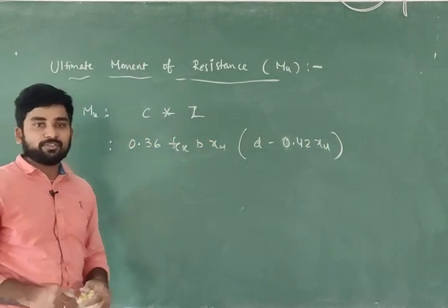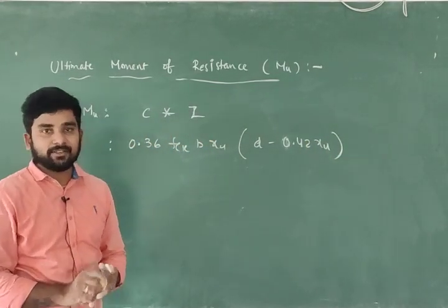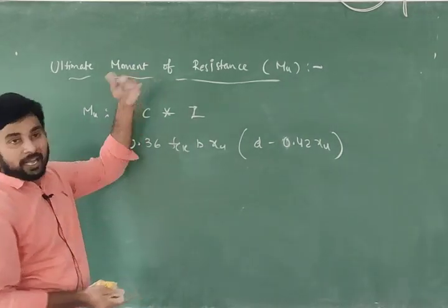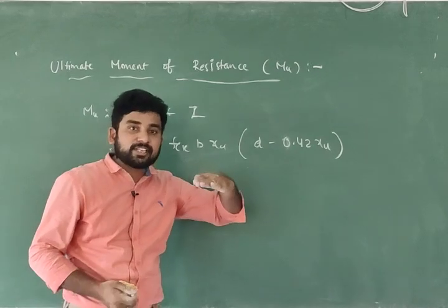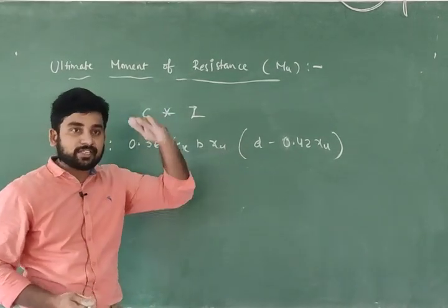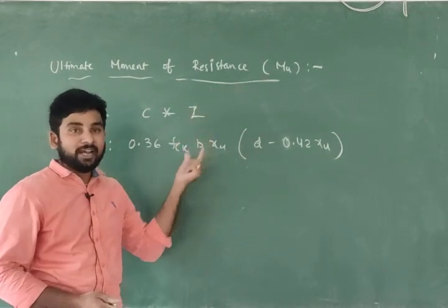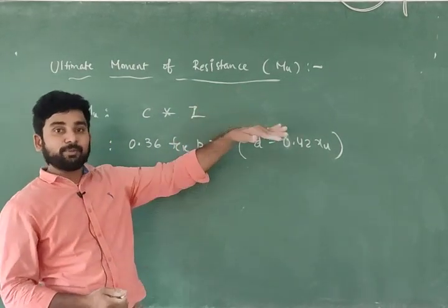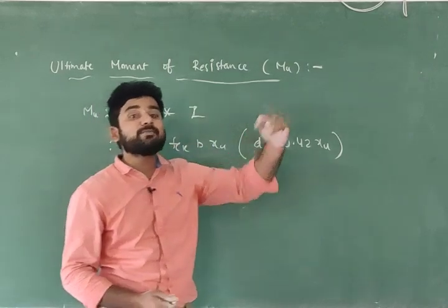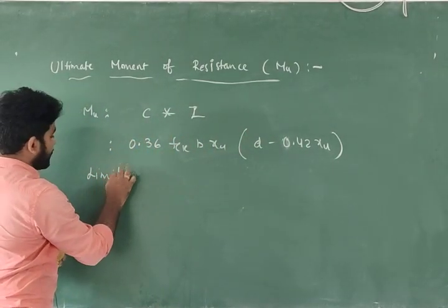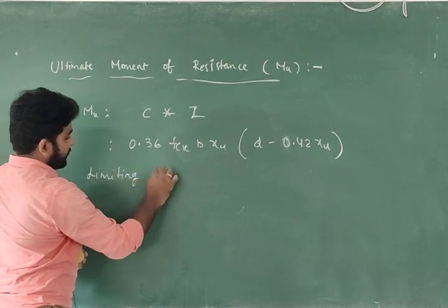This is my moment of resistance of section. Now what I am doing is, I want to find out the moment of resistance, here also. I want limiting moment of resistance, like Xu maximum. I want the maximum moment of resistance or limiting moment of resistance.